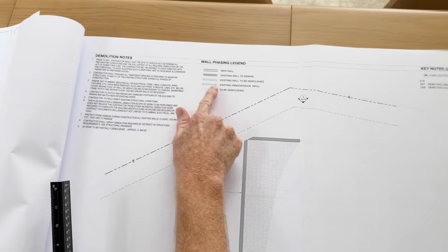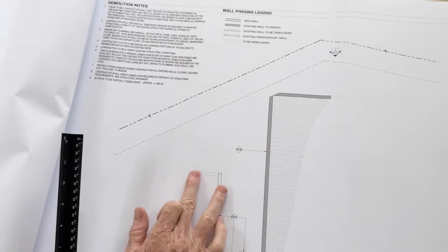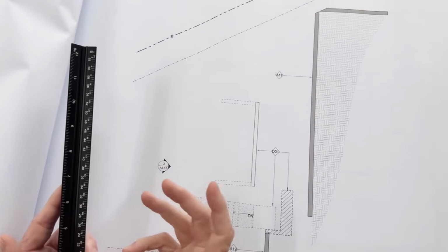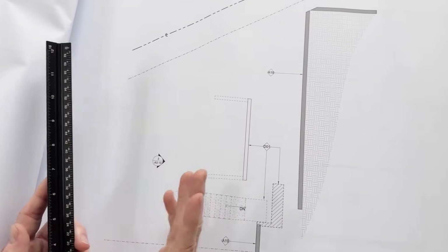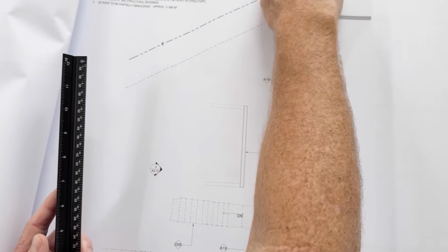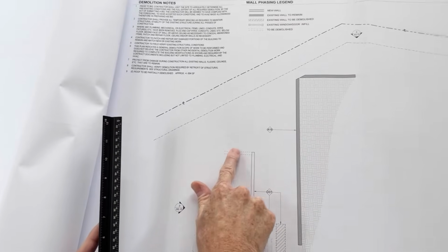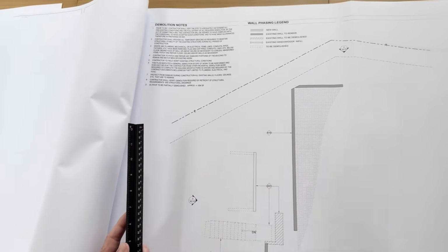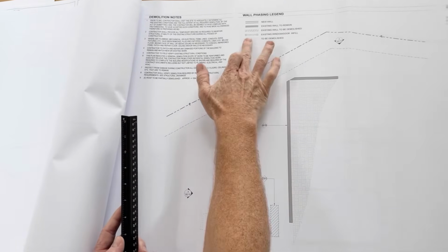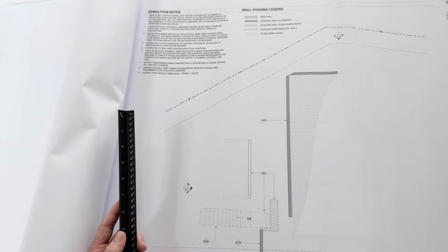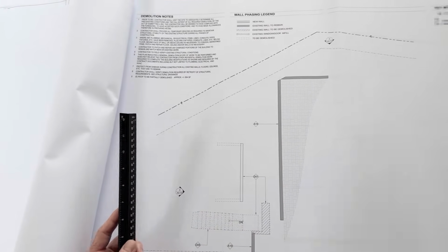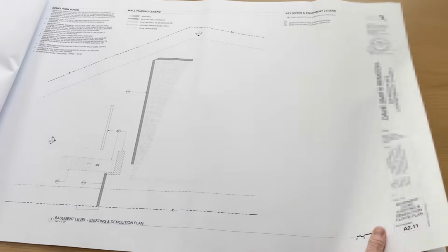So we want to find those walls. So if we were marking this up, right, and we were trying to figure out what walls remain and what walls go, this wall is a new wall, okay? You can see this is a brand new wall, and there was a wall here that goes away, okay? So anytime you have a dash mark like that, it means demo out. All right, we'll get a better example of it on the next page.